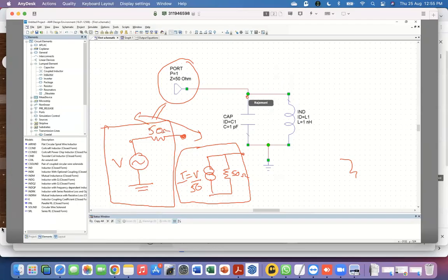So it's like as if a resistor was connected to this. That's how this circuit will behave. So you can see another important aspect, and I will be coming to this particular point over and over again throughout the course of this lecture, because this is something which is non-intuitive for people who have worked only with low frequency circuits, that connecting a microwave port or a microwave measurement device to a circuit always introduces this 50 ohm to ground. This is not true for low frequency circuits, right?